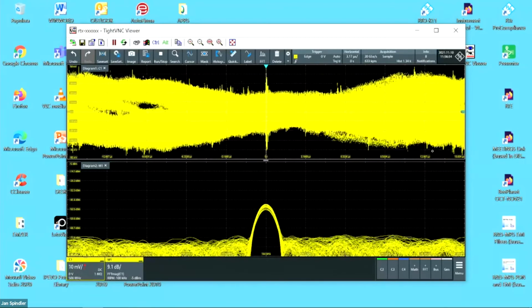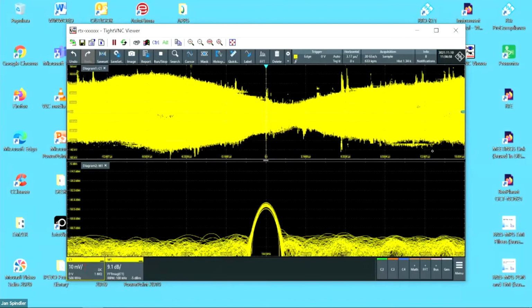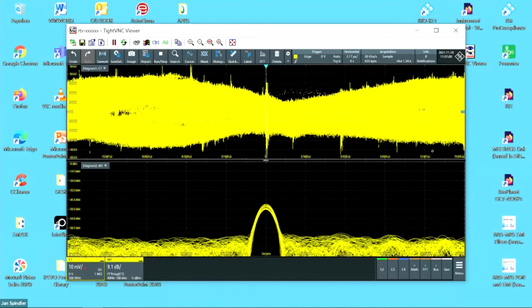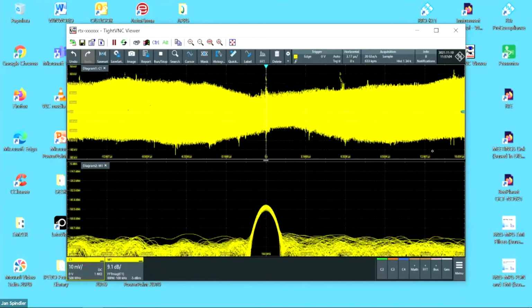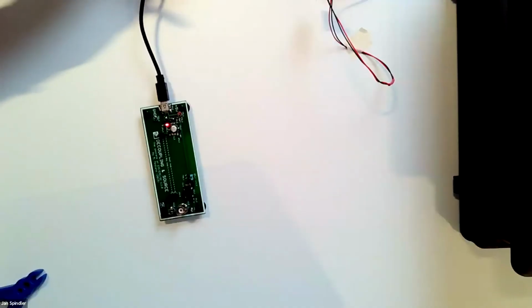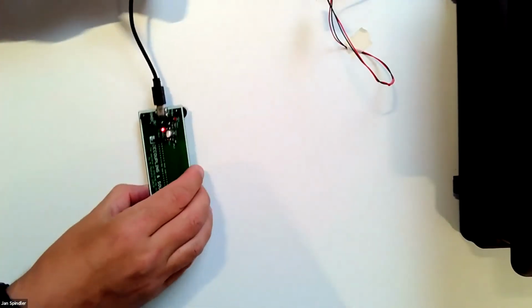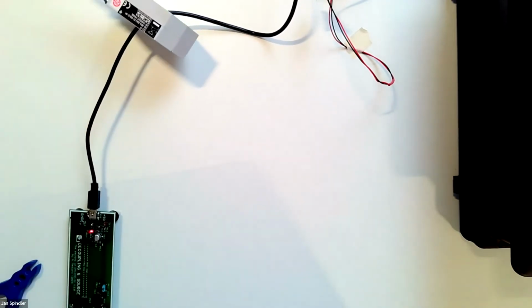No, remember from yesterday, my problem is not differential mode currents. My problem is common mode currents. So you open the current probe and you go here to measure the common mode current in your circuit. This is what I am doing. Okay, let me put it here. Something like this. You see the current probe and you see the power supply cable.